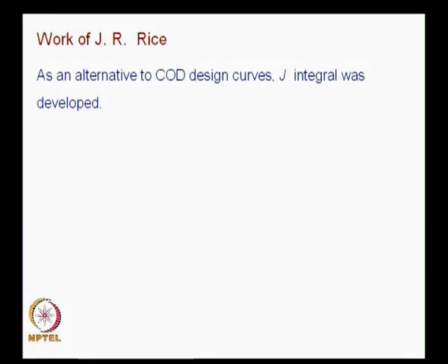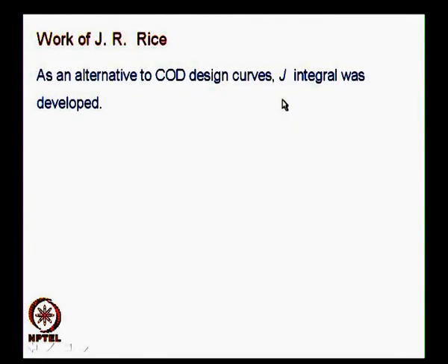So, one of the earliest approaches in that was CTOD, and I said crack tip opening displacement, you have to understand the terminology. We would postpone it for the time being, but we would definitely see as part of this chapter. And while discussing J integral, you cannot avoid CTOD. So, you take that as crack tip opening displacement for the time being, and we will first develop J integral, then get back to CTOD. Historically, if you look at COD was developed earlier, and J integral got developed later.